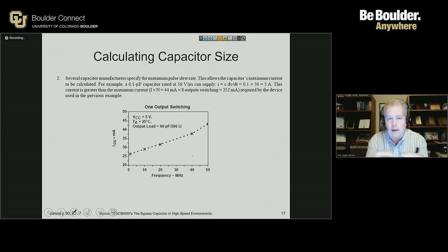And if you have a capacitor which is working very hard, which it does maybe in a switching regulator circuit, those ESR and ESL components can influence how hot that component runs and whether it maybe fails early because of the thermal load.